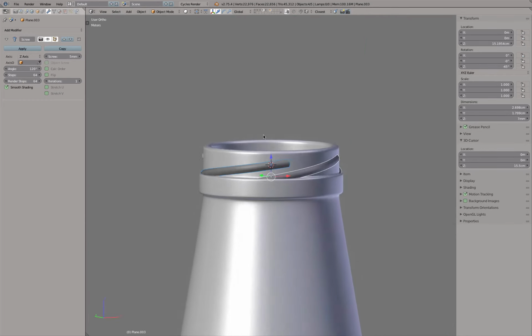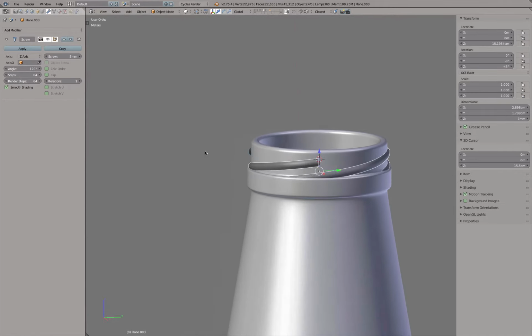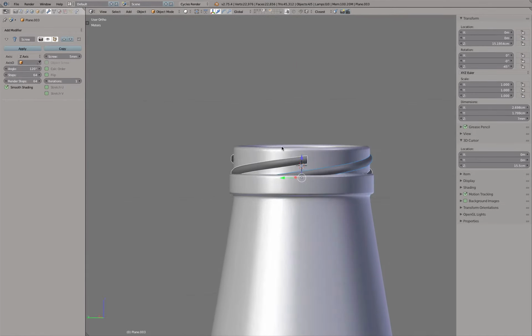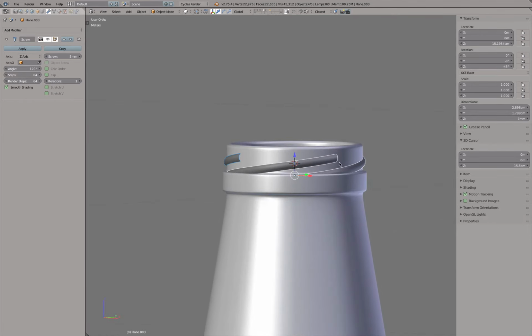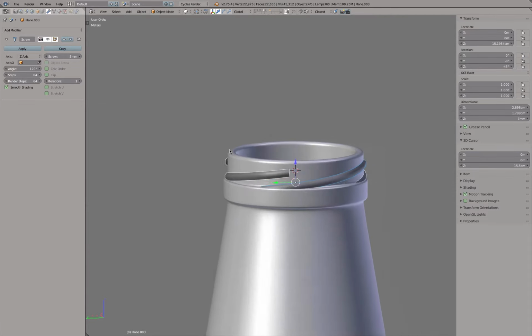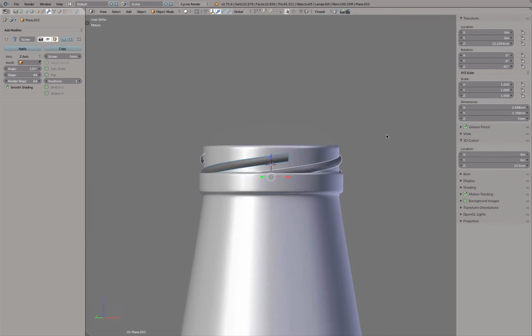Just the blue one got changed, but not the rest. So what we do actually, you hold Alt key, click into this value, and then type in 120 and press enter. That actually applies the 120 degree change to all objects we have selected. And take a look at this. Yep, this is better now. We see actually here there will be an interlocking mechanism. This is exactly what we are looking for. Pretty good. Yeah.